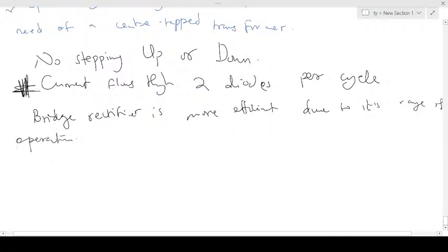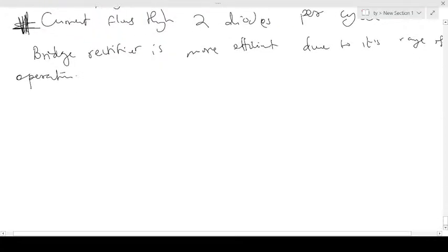However, the voltage drop. Previously we talked about voltage drop, where the voltage is altered by the barrier potential. We stated this when we were covering the half-wave rectifier: one of our assumptions was that this was an ideal diode, but in a practical diode, due to barrier potential, there will be a 0.7 volt drop.